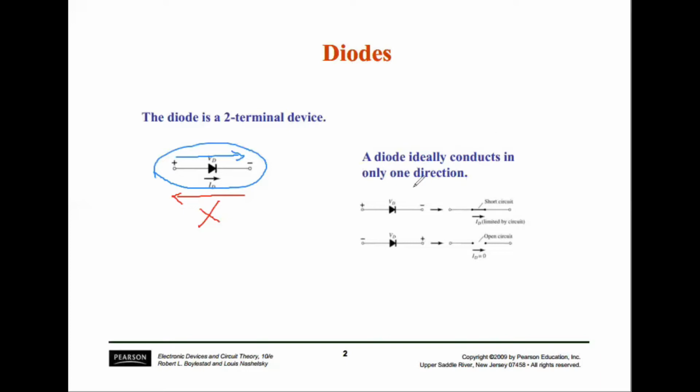section. So you can see that when a certain polarity, like positive, is applied here and negative is applied here, the diode will be conducting, acting like a conducting wire, and it will be represented as a short circuit in ideal circumstances. Okay, ideally we consider that it doesn't have any resistance, so that's why we will be considering it as a short circuit.